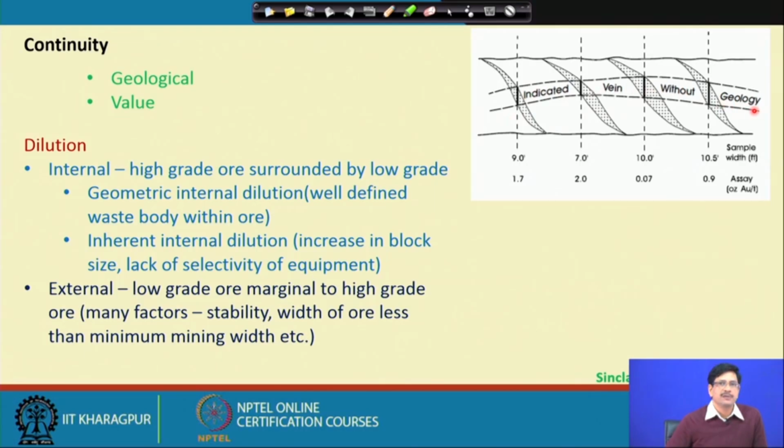One can then calculate the extrapolated volume and, with the density, a tonnage, which will be grossly wrong, because what will be calculated as a continuous ore body will be far more than the amount of ore present in such separated sigmoidal veins. There are many such examples which could be cited.